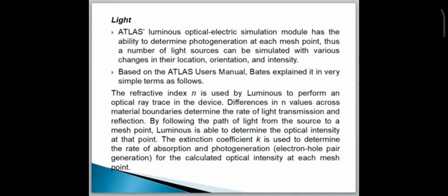Next, you have to define the light statement. Atlas Luminous optical electric simulation module has the ability to determine photogeneration at each mesh point. Thus, a number of light sources can be simulated with the various changes in the location, orientation, and the intensity. Based on the Atlas user manual, Bates, one of the researchers, explained it in very simple terms as follows.